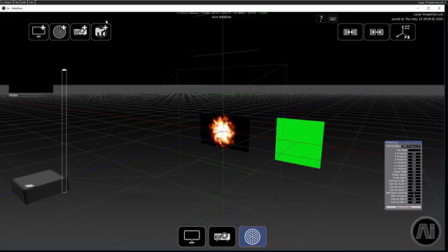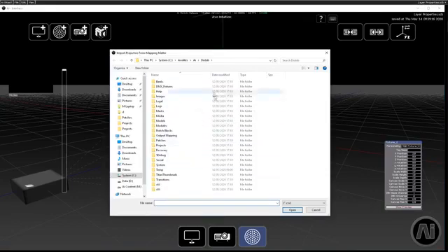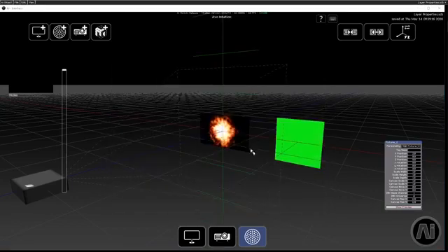Mapping Matter lets you calculate your heat maps, your projector positions and your lens settings and ratios, all that kind of thing. When you use the Mapping Matter fixture, it will let you load your Mapping Matter preset and apply it to any of the existing projectors within the project, and if there aren't enough projectors to mimic the Mapping Matter project, it will bring in more projectors so that everything is set up as you had it in Mapping Matter.